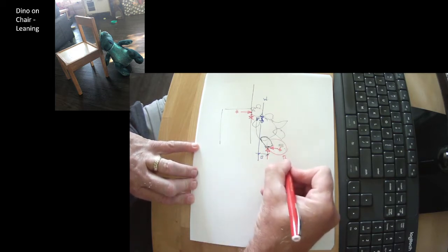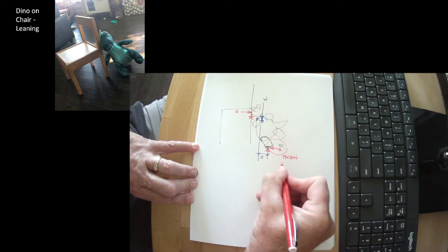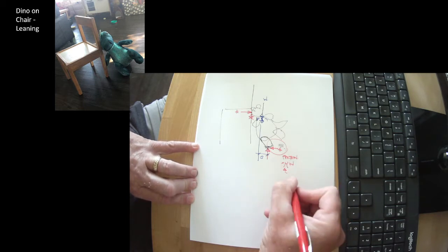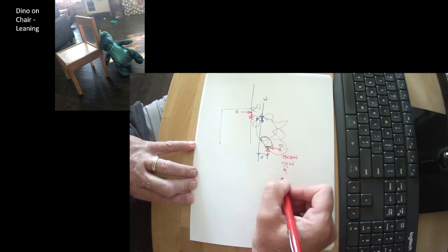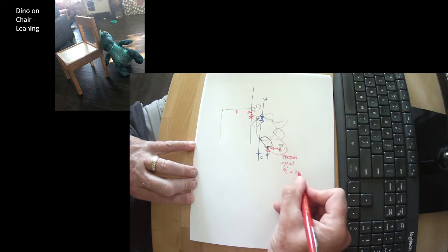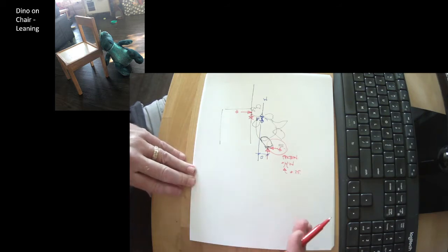This is friction equals mu W, where mu is the coefficient of friction, and you're not out of line to say it's around 0.25. That's a reasonable range. It could be up to 1. It's never more than 1.